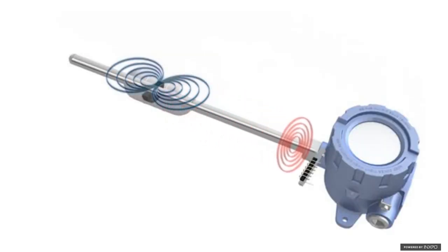So now you can see the electrical pulse, and then you see the return pulse. And again, this is a time of flight measurement. It allows it to be a very accurate measurement given the way the technology works. This technology is not only used in level measurement, it's also used in other industries to do position measurement and other kinds of applications.